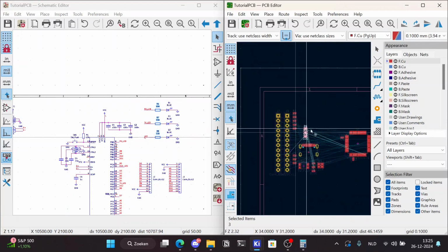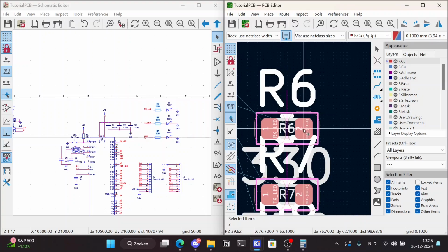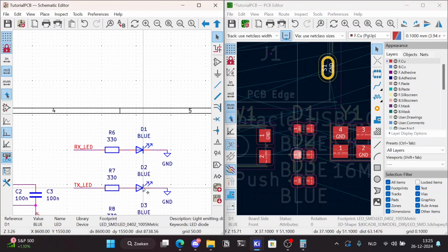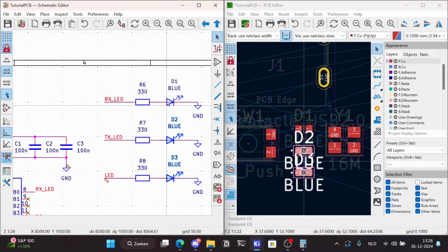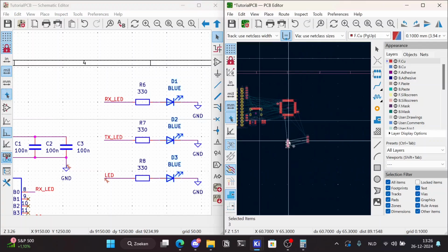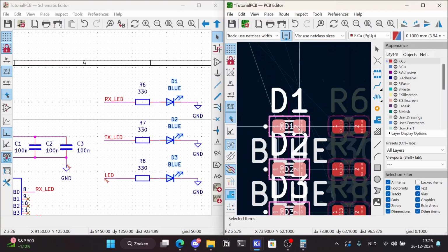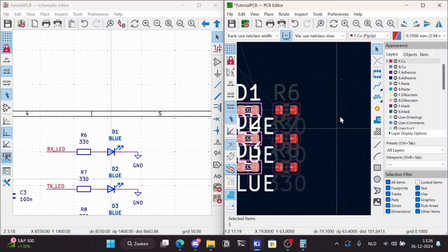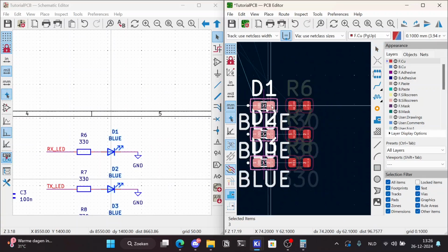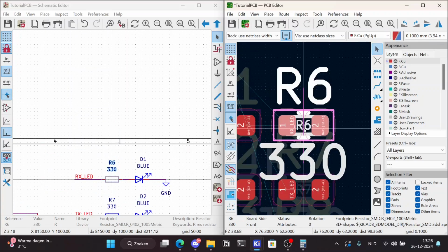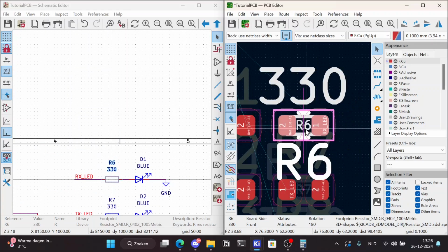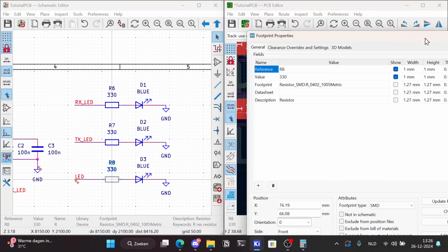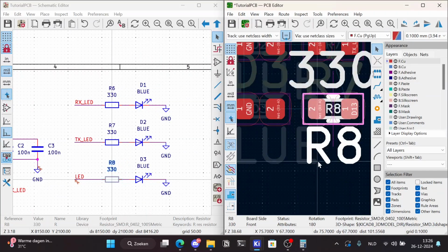We'll start first assembling it as LEDs. So that means we will do this first and find a reference for D1, D2, and D3. In this case, you can hop into a schematic editor and do your thing. However, please be noted that this is not the direction we intend for. This is reverse. So you have to press again. You can press R as usual, like in the schematic editor, until you reach your desired direction.